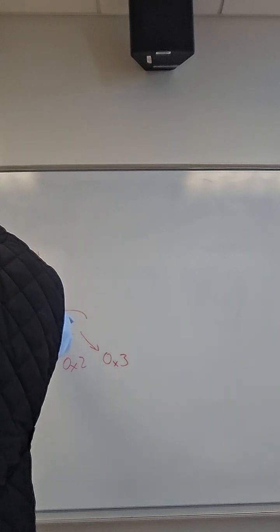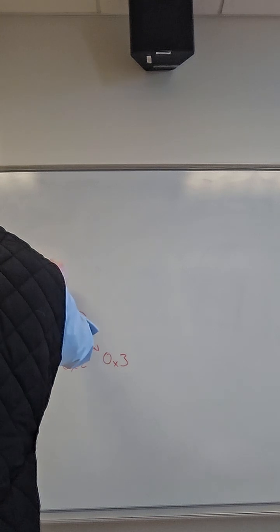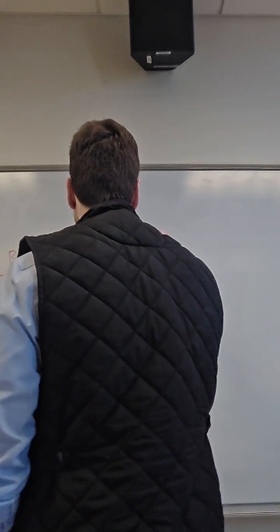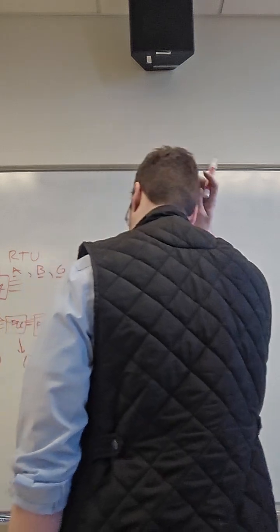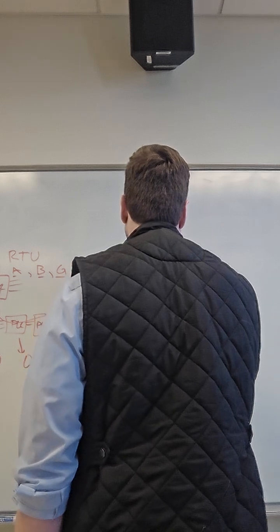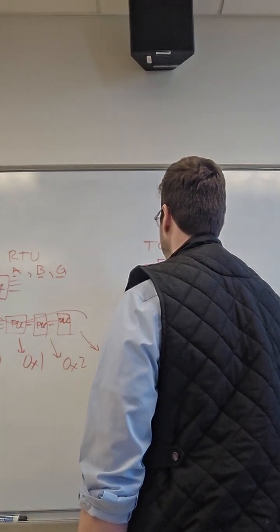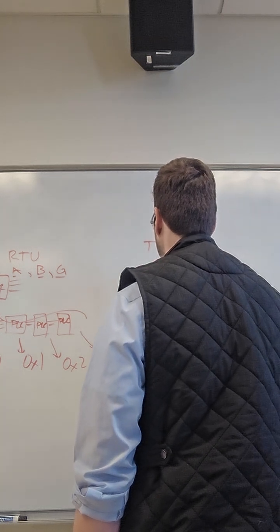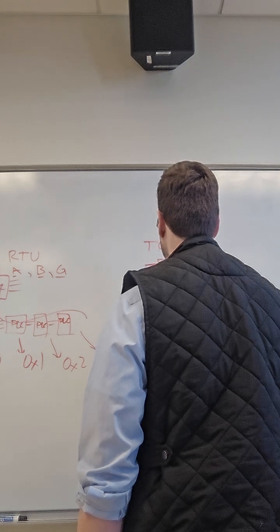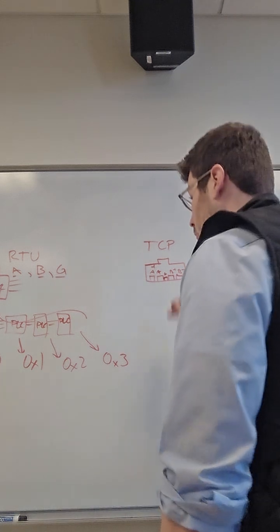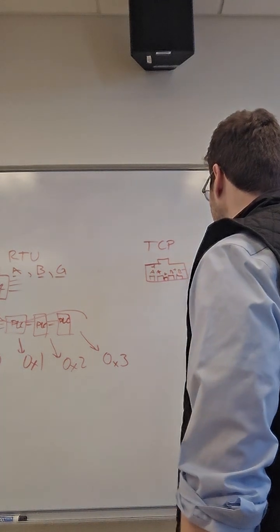That's where we have our A line, our B line, and ground. Literally just 3 copper wires needed for that. TCP needs a whole lot more than 3 wires. TCP actually uses Ethernet, so it uses the Ethernet jack. That uses different protocols. I'm pretty sure that uses A plus, A minus, and B plus, 2 twisted pairs at the very least, and ground. So more ports besides, but a pretty standard jack.